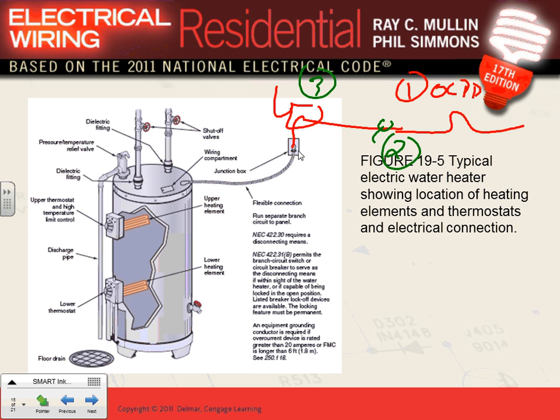What did you guys do when you circuited your water heater? You have to provide an overcurrent protection device, typically 30 amps for a dwelling. Branch circuit, 2 hots only because it runs at 240. So you have a branch circuit of 10-2 with a ground, and a disconnect unless the overcurrent device is within sight of the appliance. You have to provide a disconnect.